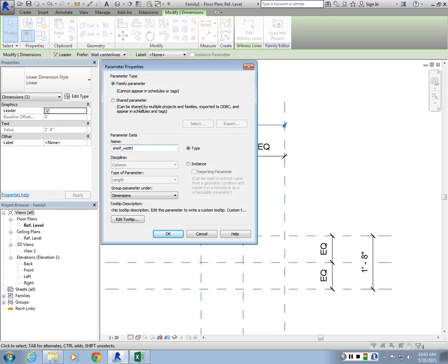Shared parameters are normally used for when multiple families are nested within each other. So you can have reporting parameters to be used in another family. So like, let's say louver-based systems could be hosted by curtain walls, and you want the curtain wall family to see the louver parameters as well. So you want to change their properties to be shared parameters so that you can access them within the other family. We're going to look into those later. So just choose family parameter.